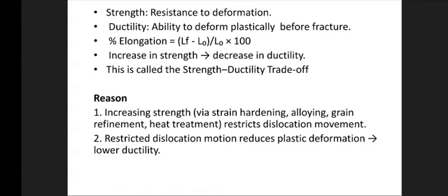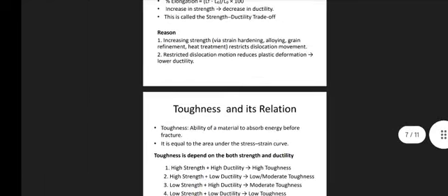First, strength is increased by processes such as strain hardening, adding alloying elements and heat treatment. In these processes, the movement of atoms or dislocations is resisted, so the strength increases. Next, when the dislocations are resisted, plastic deformation and elongation are reduced, so the ductility will be lower.